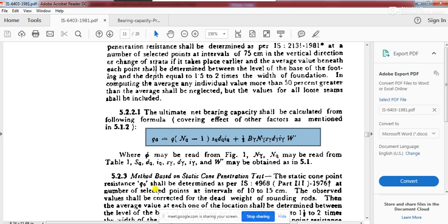Because it is a cohesionless soil, c is zero, so the term becomes zero. Yes, you have got it. Correct. So that is why, as I told you earlier also, everything is coming from the basics of Terzaghi. If you understand Terzaghi's bearing capacity formulation clearly, the Indian Standard Code formulation is almost following the same, with some more assumptions introduced using Meyerhof's formulation.